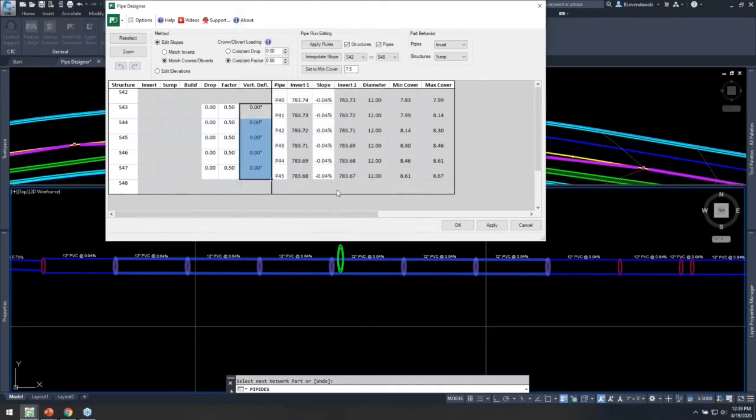So I've got vertical deflection. I'm not gonna put bends in here. I'm gonna attempt to just slope this water main down and then back up to avoid that storm line. But my deflection is, of course, a concern in dealing with that. So let's grab these 2 pipes, this one here and this one here. We'll slope them down, and then these 2 we'll slope back up by a similar amount.